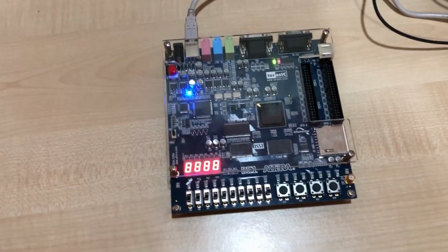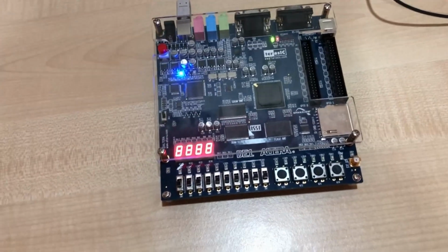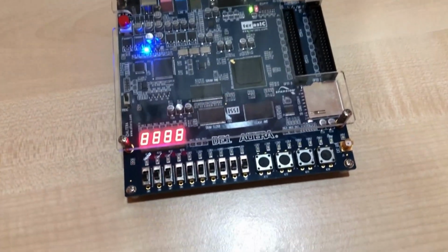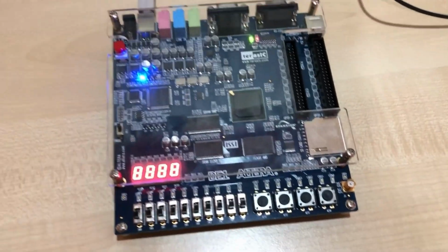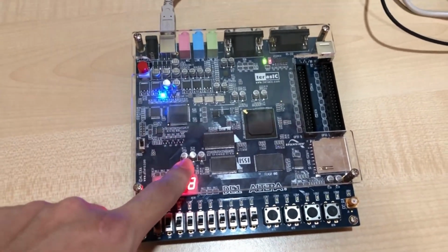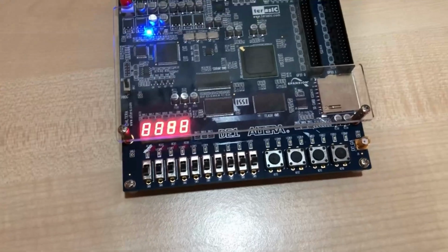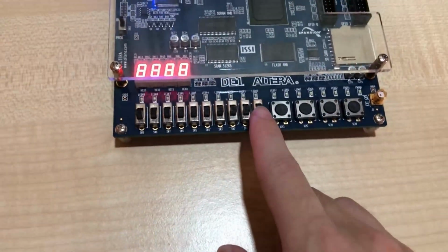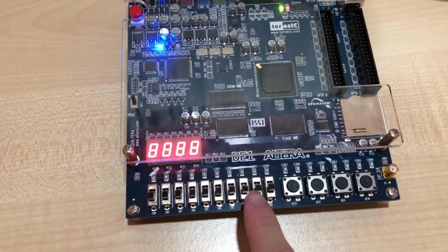Now comes my part 2A, which is the hardware modeling. The 5 D flip-flops and the XOR gate have been connected and compiled into the DE1 board. Also, the 50 MHz internal clock from the DE1 is already slowed down to 1 Hz, so later we see the light is slow. Here we have 2 inputs, which are the start button and the reset.